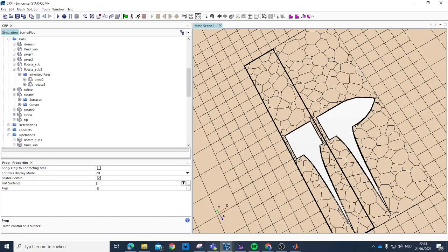And then the second reason is the mesh between those two propellers has to be a lot more refined than in the front of the propeller or the sides. The sides can also be refined, but this region in particular has to be really fine. So I will also make that change to it. That will also be used for the duct simulation, but that's later on.